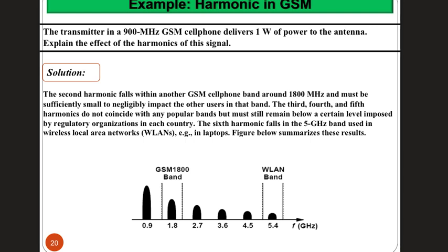So again, if I am a manufacturer of that cell phone, I have to make sure that it does not affect my system, and also it does not affect other systems. It does not affect my system because the main user of the cell phone, the carrier, is not going to allow me to put that into their network because it's affecting other users. But there are also certification entities that deal with different frequencies allocated to different technologies. So FCC, CRA here in Qatar, and so on, right? If you bring them a device that causes harmonics to other technology, they will tell you forget it, right? It cannot be certified, you cannot operate that device.